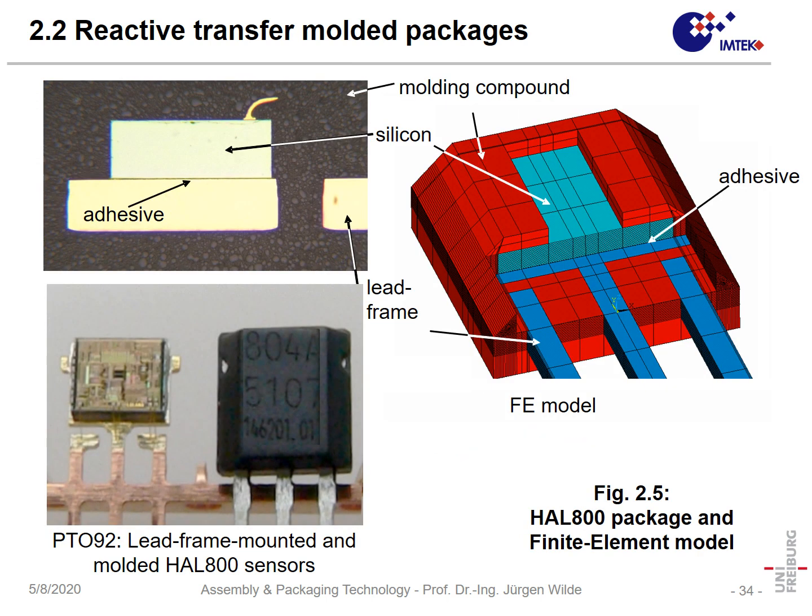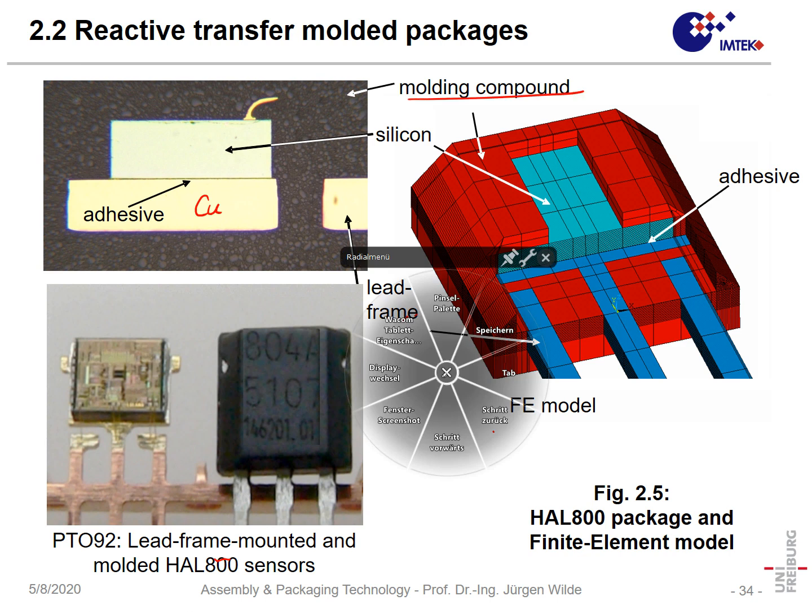Okay, here we see a cross-section. First of all, that's the device on the lead frame, and that would be the device after it is molded, after the leads have been tin coated, and after we have laser written some data on top of that device. Here we can see a cross-section. That here is a copper material, that is the silicon, and that here is the molding compound.